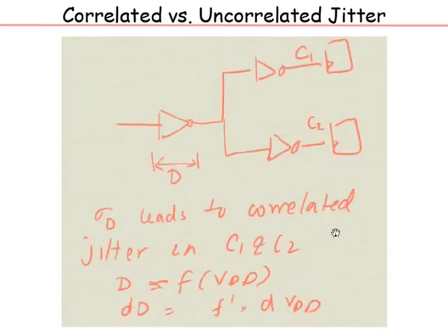Again, you make sure your sizes are large, because there is thermal noise. Thermal noise you can reduce by increasing the sizes of devices. In addition, in your clock distribution, you try to have as clean a supply as possible, or make delay cells which are less sensitive to power supply, and so on. The other thing also is the edge rate of the clocks. If the edge rate is very poor, remember, as we discussed in the last class, any change on the voltage side leads to a larger change on the timing side. So again, you want to have sharp edges to reduce the timing jitter.